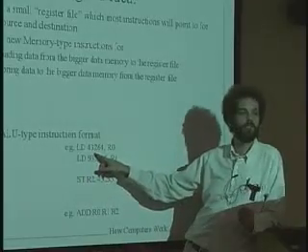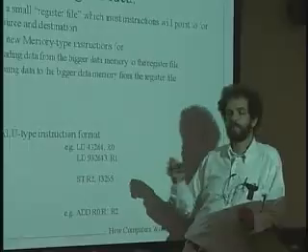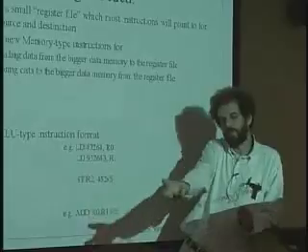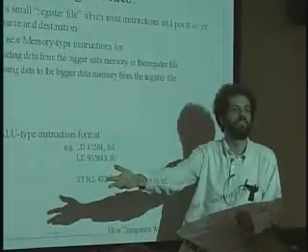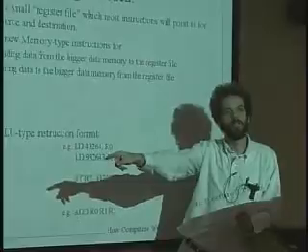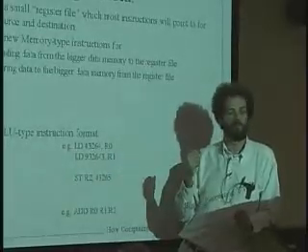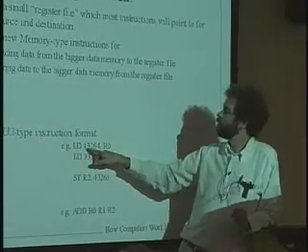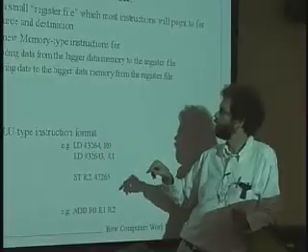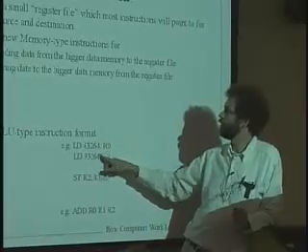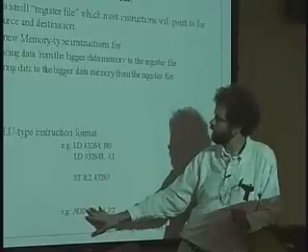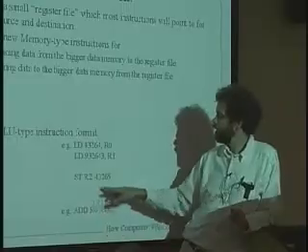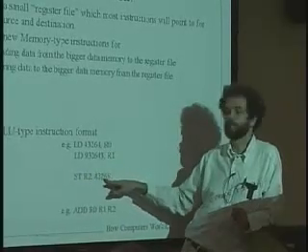And load is going to be an instruction to bring something into the small memory. Keep in mind, again, it's a kind of calculator-centric view. So I load something in and I store something out, okay? I store it out to the main memory and I load it in from the main memory into the register file. And so I'm loading from location 43264 into R0 and from this location 1. Then I would typically take this add statement and put it in the middle here. And then after I was all done, I would put R2, storing it into location 43265.